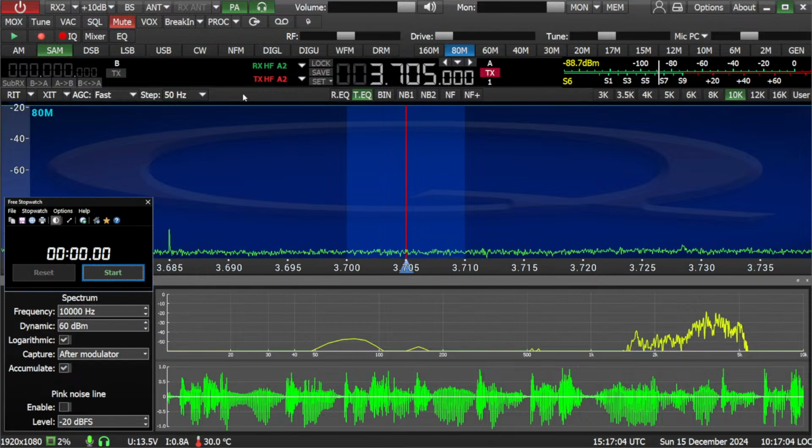That entire process is done. Of course, you got your receive bandwidths here, and you can set a user bandwidth. Now, something I have found, which is very handy, I don't know if you guys use this, a lot of times you'll get these guys that throw carriers in within the bandpass. So this is your bandpass on 10 kilohertz, 5,000 per side, and you'll see a carrier pop up.